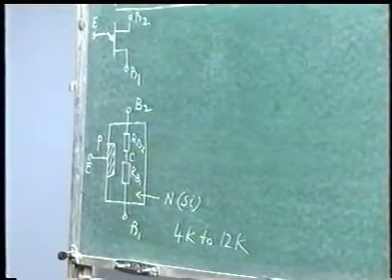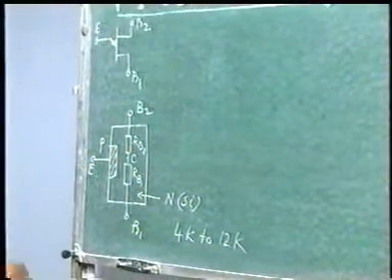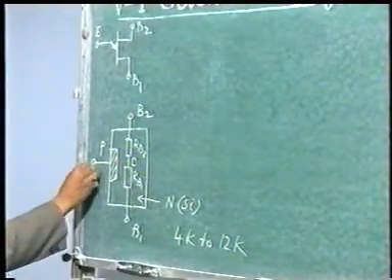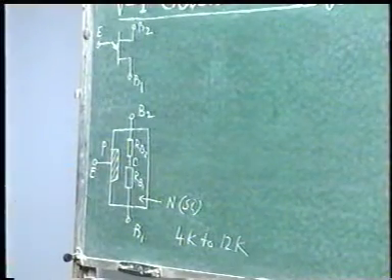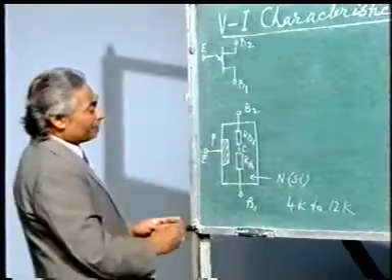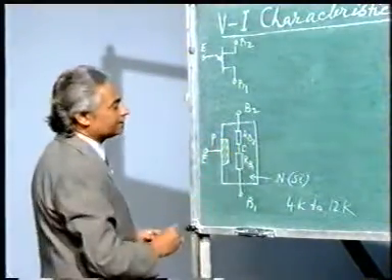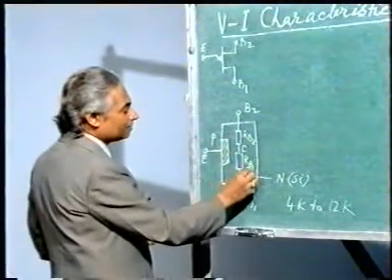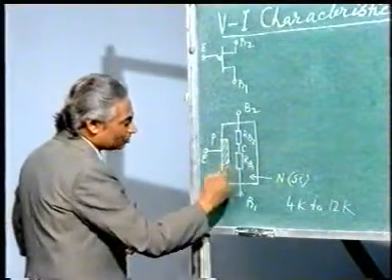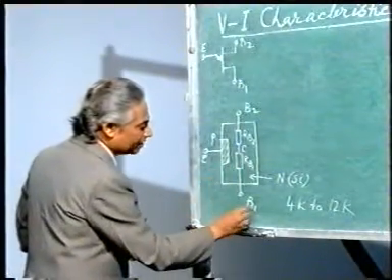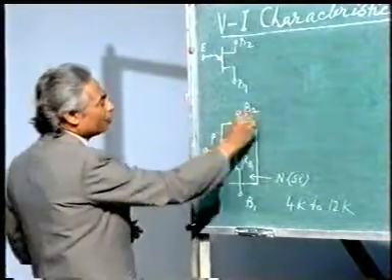When a p type material is diffused in it, a junction is formed, and from that junction another terminal, which is emitter, is taken out. From zone 1 we have one base terminal, we call it base 1. From zone 2 we have another base terminal, we call it base 2.